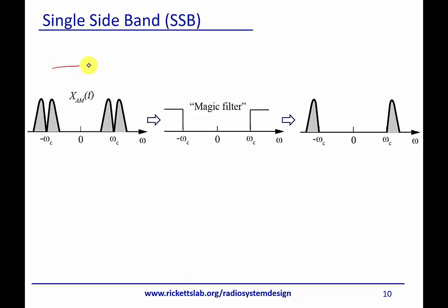Well, if you remember, our original signal looked like this. When we up convert it, we get this half and this half. Here we knew that these two were just a mirror of one another. This is omega equals 0 right in the center. One was just a mirror here, but if you look at it now, we've got 4 copies of this, but we only need the 2 halves to recreate the signal.